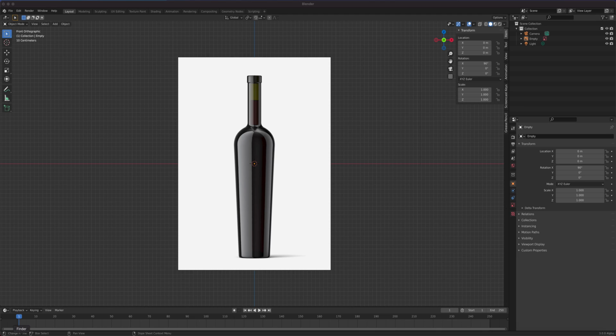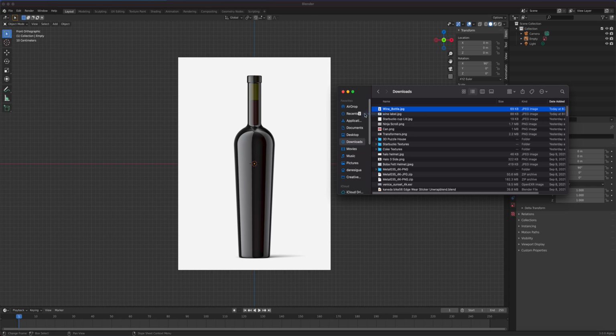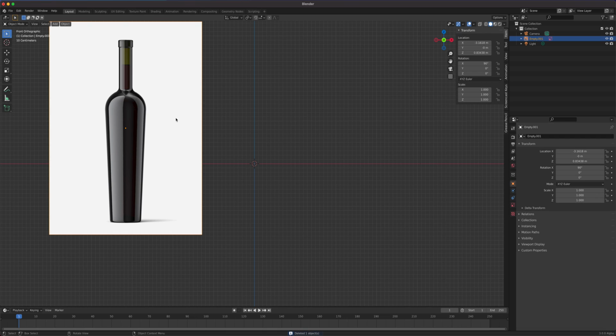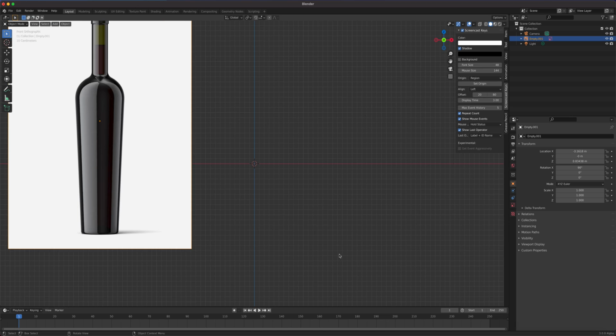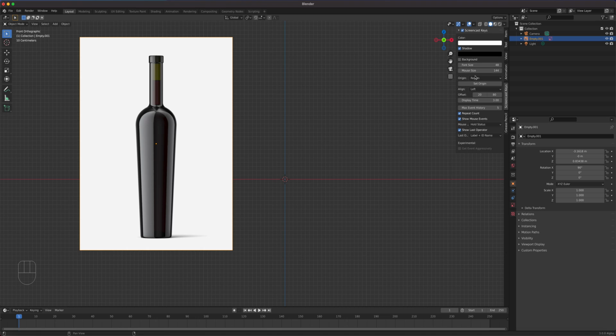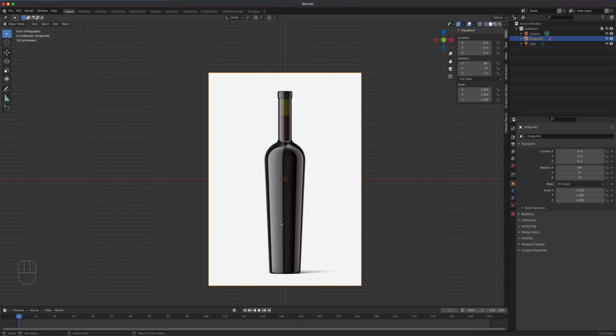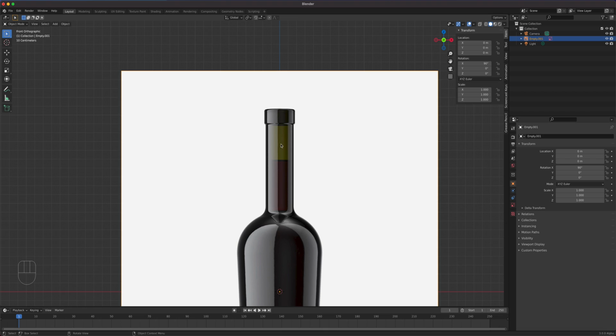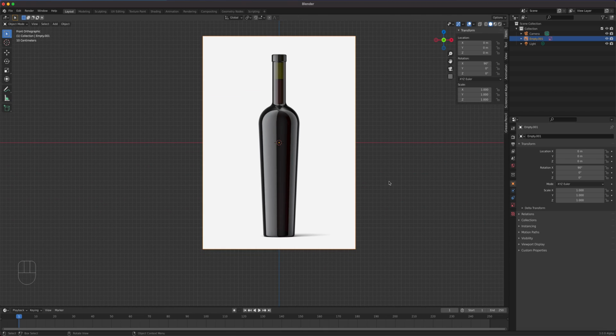This is basically just drag into the screen like so. Okay, and then let me delete this. What I did with this one is centered it on the screen. So let me just make sure my screencast is working. All right. I'm gonna press N for the sidebar, and I'm on item right there. So you get your XYZ location for the image, which is the empty. I'm gonna click and drag here, and I can put in 0 so that it's centered on the screen. And I'm assuming here that this is aligned perfectly. It's centered.